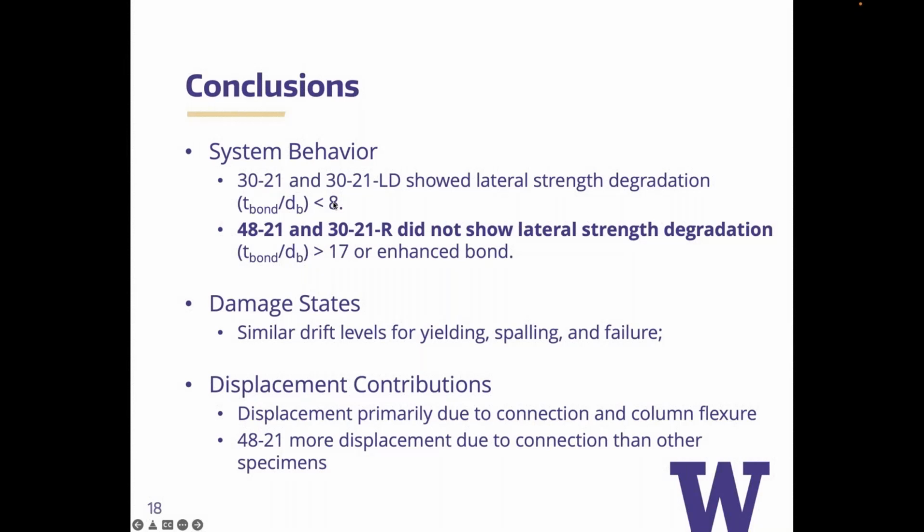And that really gives us something to think about when we think about eccentricity in terms of reinforcing bar cage placement: with that eccentricity, even if you move that cage closer to the steel tube, having that ring will give you that enhanced bond. And so eccentricity becomes a lot less of a problem.